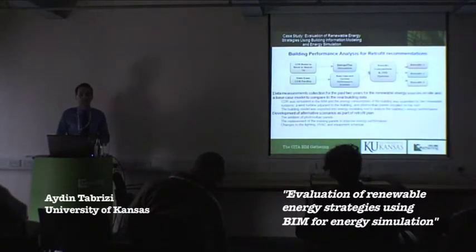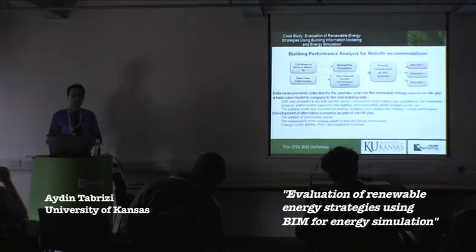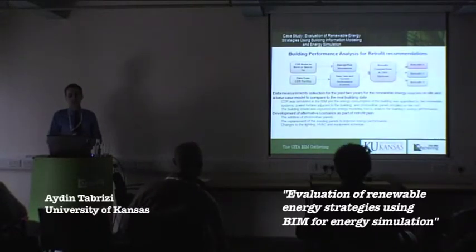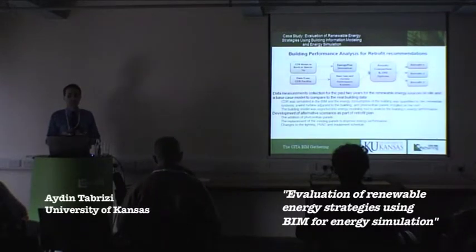So in this graph, basically, you can see the process that we developed, as I mentioned. Data collection and the CAD model in Revit. Then EnergyPlus was used in collaboration with Revit to analyze, and the base case and current performance of the building were obtained from the data from the Facility Manager. Then the results were compared, and 3 retrofit plans were allocated as different scenarios for this project.